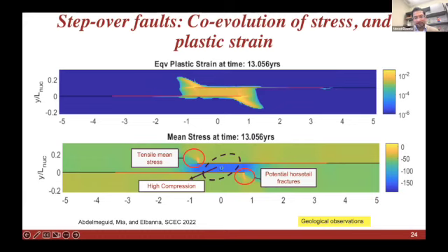The mean stress that we started with here was 50 megapascal. After many cycles, it can actually reach 300 megapascal here. And if we keep simulating, it increases more. So we are also learning about limitations of the constitutive model. How does rock behave under increased confining pressure in that way? If we start with Drucker-Prager plasticity, is it actually valid as we push it further, or do we need to engage other constitutive models like damage or fragmentation and so on?